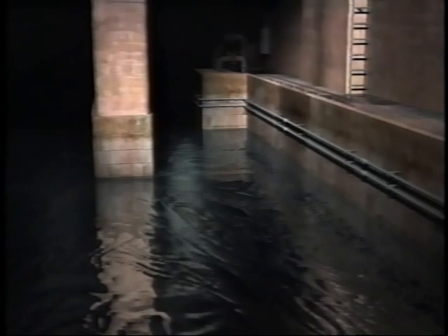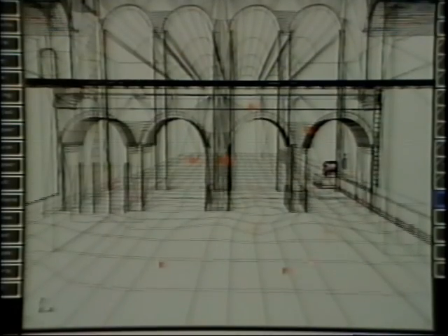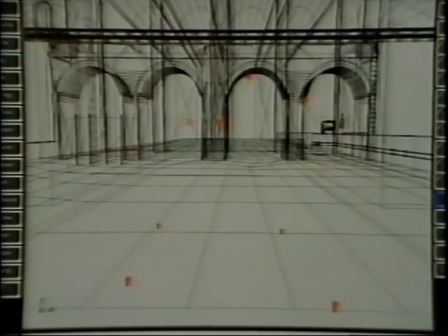Another water-related effect that's happening in the scene is the impression of light being reflected off the water back up onto the walls. Now, the walls that receive this light are not reflective themselves, and radiosity is not supported in the renderer, so we have to fake the reflected light effect by projecting light up from underneath the water.